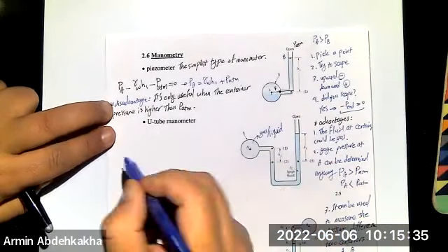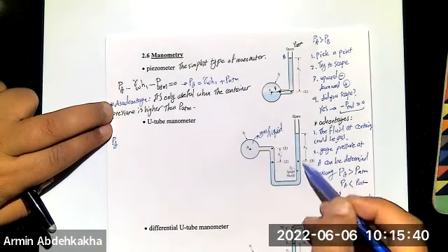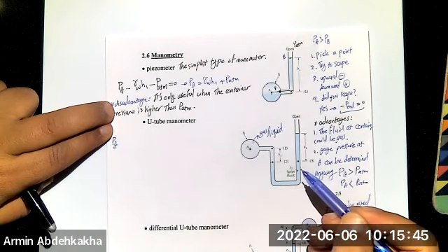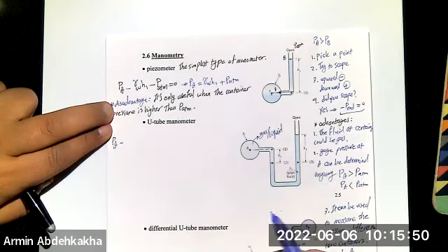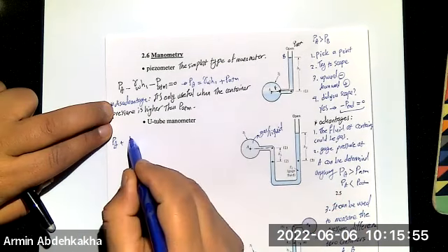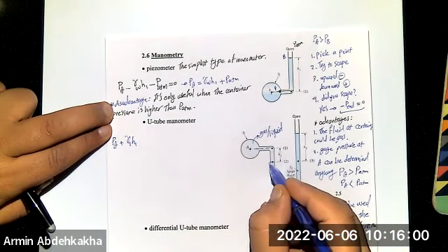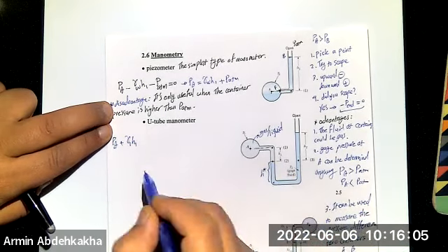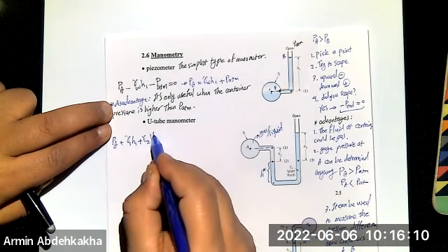Point A. PA is selected. Then try to escape. This line is going to be your line for escaping. Then moving to point A, nothing changed because these two are the same line. Going to point 2, it is positive because going downward. What is the gamma? It is gamma 1, and H1 is the amount, right? You don't know what this H is. Let's call it H star, okay? You're going down and the gamma is gamma 2, so plus gamma 2 H star.